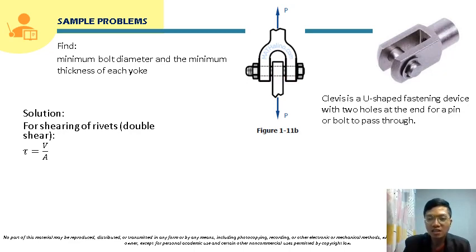The shear force here, if you solve for the internal shear force using the equilibrium equation, will just be 2V equal to P, or 2V minus P equal to 0. Solving for V, that will be P over 2. So the shear force here will be P over 2.